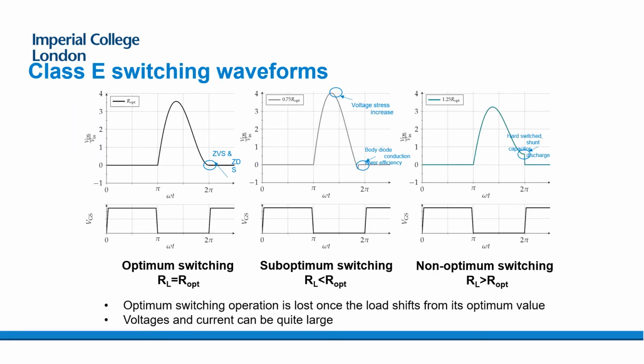On top of that, though, there are some issues still with these circuits, and in particular, what we note here is that when we design these Class E types of circuit, either the simple one or the semi-resonant one, there is an optimal load which allows us to achieve 0 voltage and 0 derivative voltage switching.